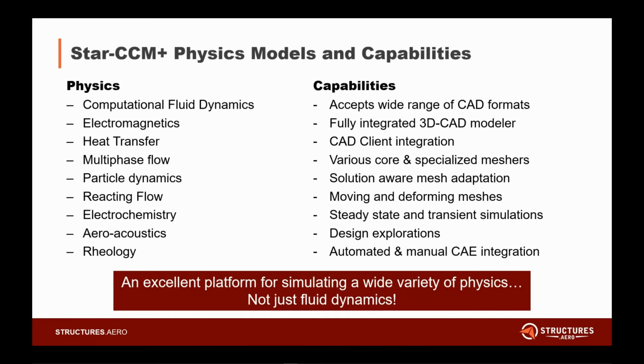You can model gravitational acceleration, steady or unsteady simulations, and different equations of state, for example, if you've got constant density or you need to treat your fluid as an ideal gas. And then there are also turbulence models for different flow behaviors, especially if you are working in a boundary layer type application.